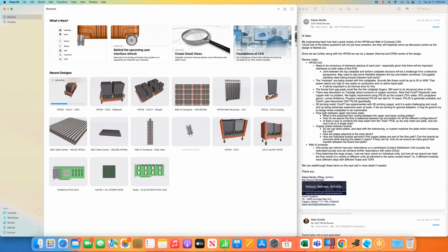We've got a column of 16 modules, and the water pipes go down through each of the 16 modules, with a cold feed and a hot return. That's pumped, and there's a heat exchanger at the top. So that's one closed loop in a vertical chain, and then the infrastructure water goes to all the heat exchangers. Okay, that's good. I wanted to make sure it's a separate secondary closed loop. Yeah, that would be the idea.